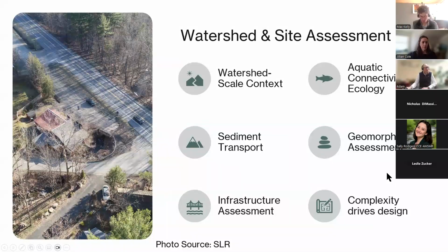that crossing. That leads you to conducting what's called a geomorphic assessment, so starting to understand the pattern, profile, and dimensions of the stream channel through the crossing, but also downstream and upstream to try to mimic the natural stable conditions that you might find above or below the crossing.